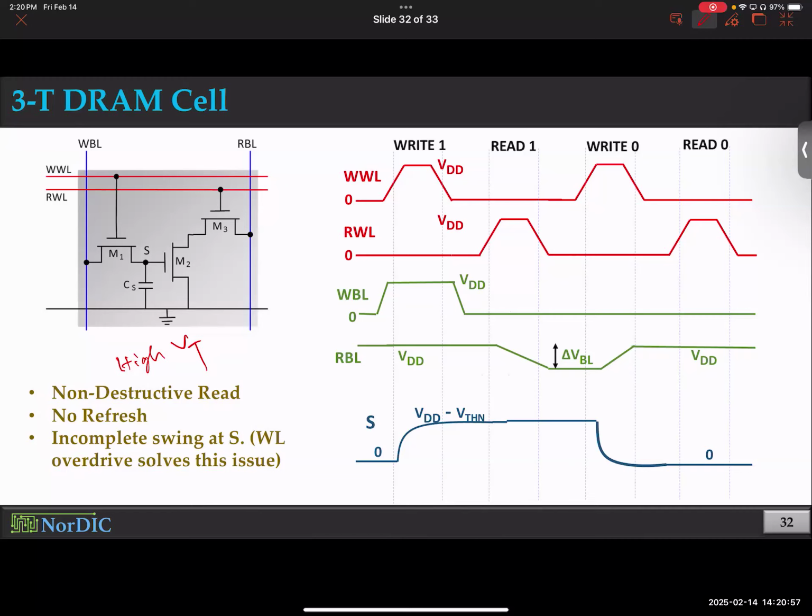I mean, am I making sense? But it's bad in the other way, by the way. Can I make the transistor fast? For example, especially when I'm gaming, can I create a threshold voltage that's super low so that I have a really high on current? Sure, but did I tell you that by changing the threshold voltage, you only change the on current slightly, but you change the off current dramatically, exponentially?